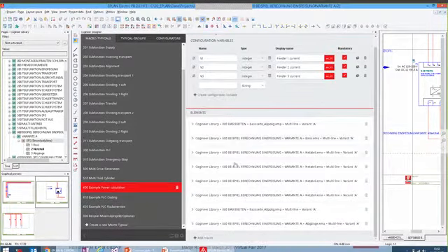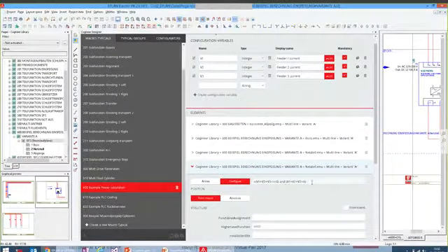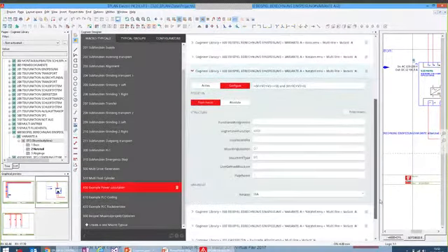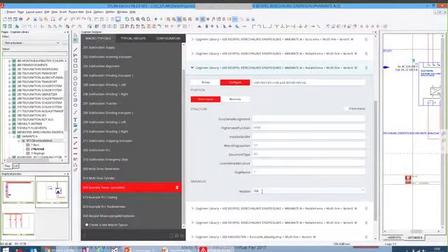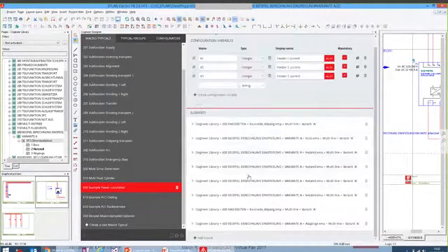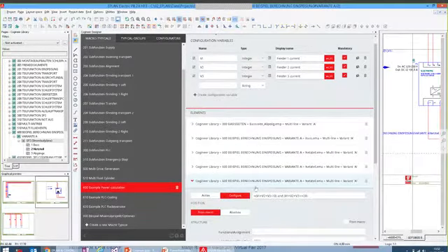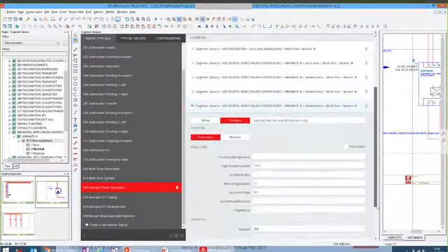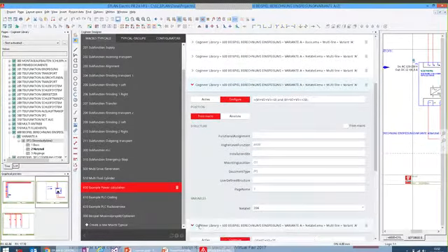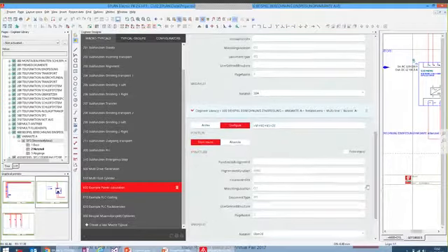But in case we are between 6 and 10, what will happen? Between 6 and 10, this condition is active, and when this condition is active, this macro will be generated into our schematic with this value. And then we can create as much scenarios as we want. If we say, okay, if it's between 10 and 20, we will use 20 amps, and even if it's above 20, so imagine that we select some values that the sum of those values is above 20, then we can easily just say here, this is over 20. So this is a little bit in the background what's happening.